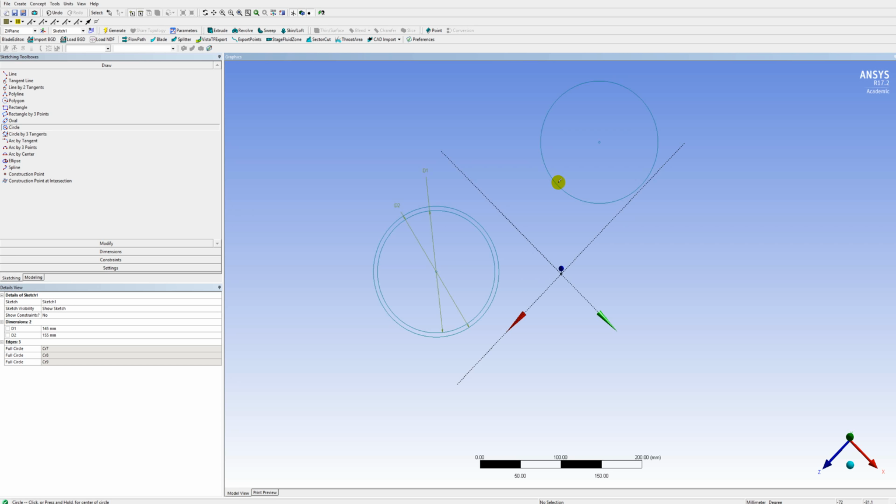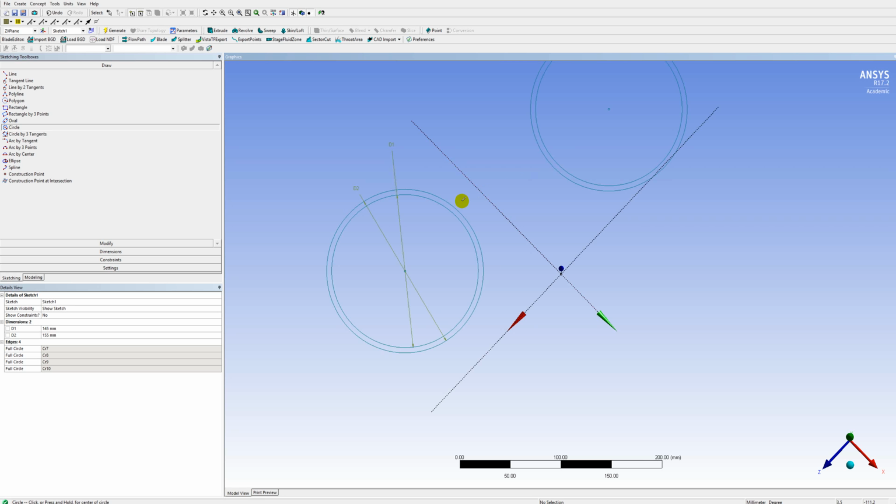So that means once you click, while the R appears, it will dimension the diameter of this circle to be the diameter of this circle. So you won't have to dimension it again. Another R will show up for the outer circle. So this cross-section is now precisely the same as that cross-section, apart from where it's located, of course.